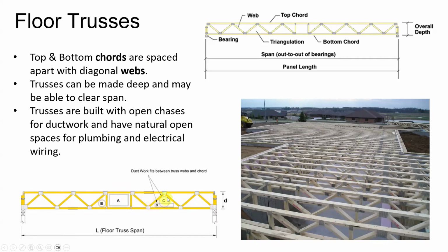So on a normal framing where you've got a solid member and you've got a plumbing pipe, you've got to drill a hole if it has to run through something. Or if you've got an electric wire that's got to go from one joist spacing to the other, you've got to drill a hole. Trusses are great. You just go up there and run them wherever you want. If you're subs that do that work or you're doing it yourself, you get a lot less labor involved in plumbing and HVAC and electrical, maybe not HVAC, but electrical, by not having to drill through all those joists.